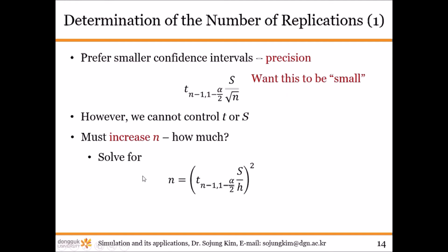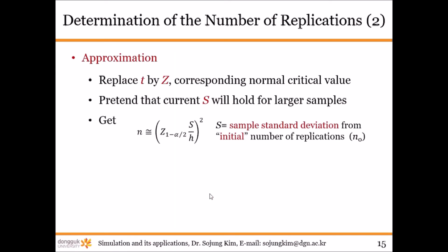And you may wonder how many replications you need to get statistically reliable simulation output. You can use this equation to specify the half width. Let h be the target half width, s be the sample standard deviation given by your simulation model, and the t value is just given by the t distribution table.